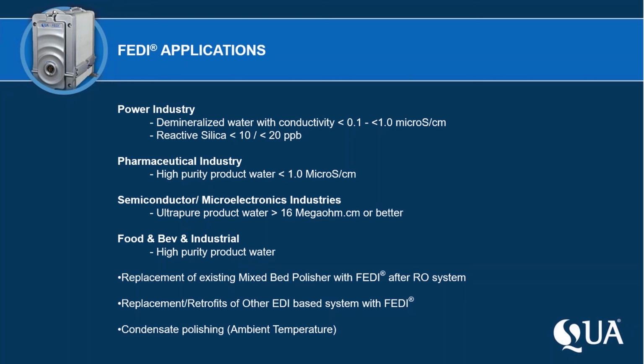And EDI actually worked very well on just media filtration. However, what you found out on some of the early systems, and I hate dating myself, but this is back in the early 90s and the late 80s, is that all these media type filtrations weren't absolute technologies. You would get breakthrough of hardness and organics, and EDI would follow.